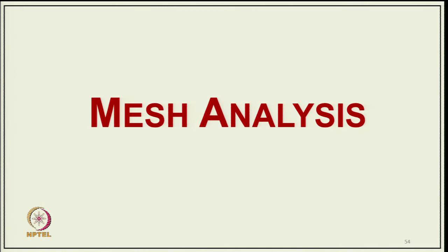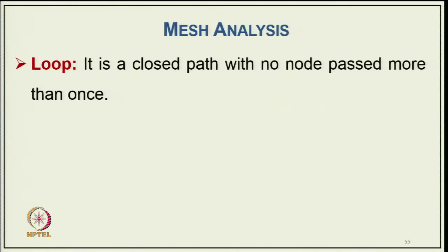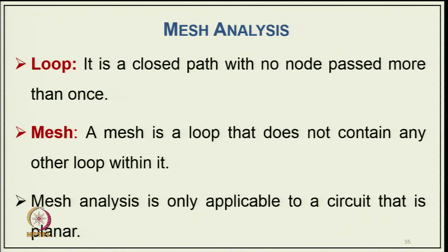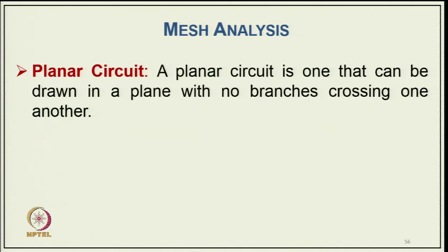So, coming to mesh analysis. A loop is a closed path with no node passed more than once, and a mesh is a loop that does not contain any other loop within it. Mesh analysis is only applicable to planar circuits.